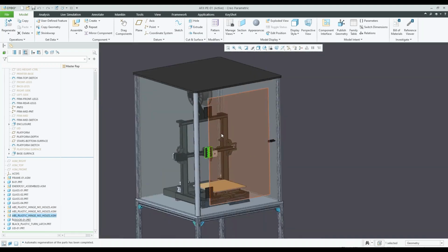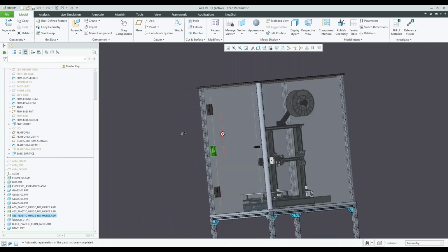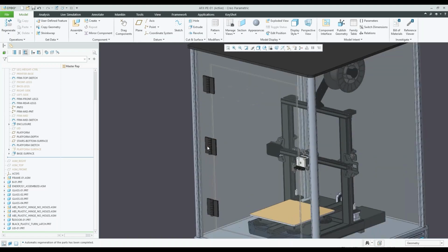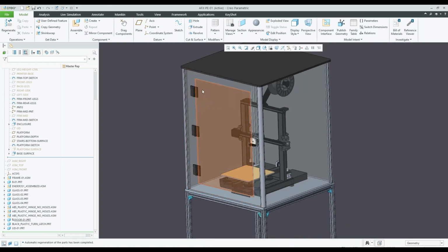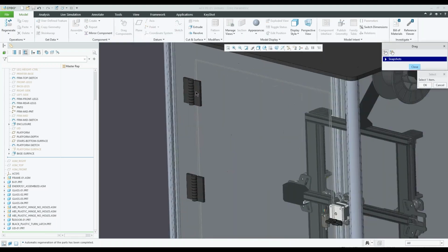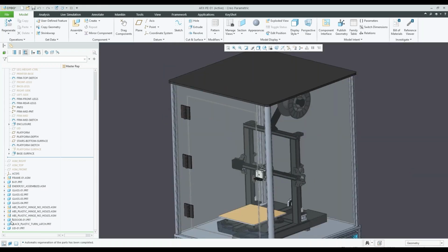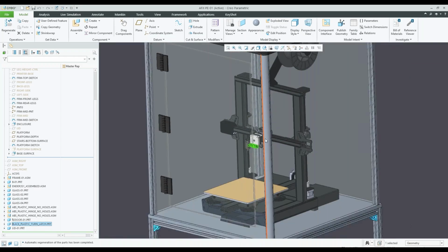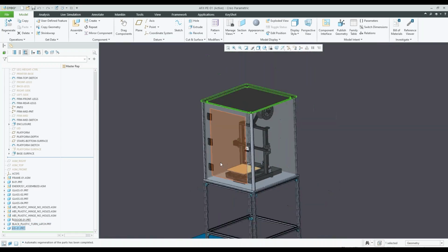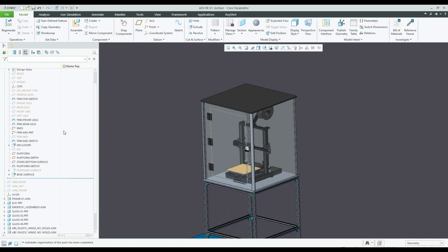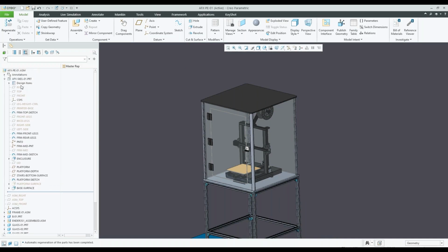So these hinges here are on that door. I used a pin connection for this one, and I set a limit. Because I assembled the door to those hinges, you can see that I can easily grab a hinge and open and close that door. Just regenerate that. I also have the door itself. I have this simple turn latch there to keep the door closed. And then I have my lid. Okay, so let's talk about the skeleton a little bit.